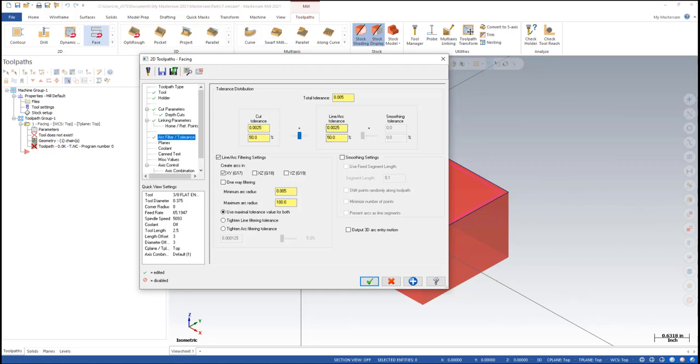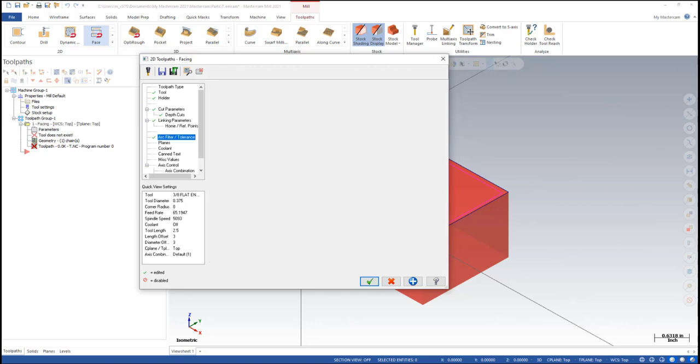But yeah, as long as it sees a series of lines that fall within the tolerance of an arc, it will convert 5 or 10 or 50 small line movements into a single arc movement, which reduces your NC file, and it also allows your controller to move a little bit smoother. But it is varying some from the drive geometry, so just keep that in mind. So we don't really need to worry about that. We'll leave it at the default, but that is an option.